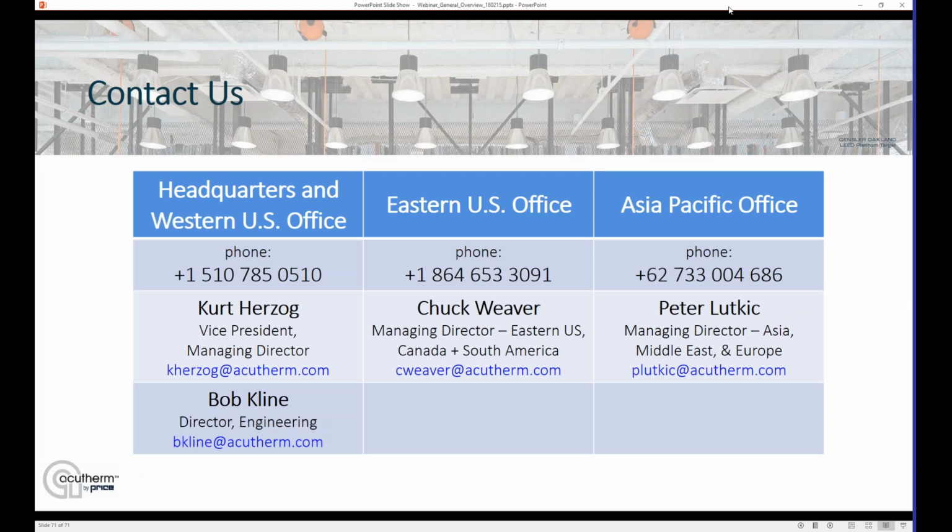Okay, let's see what we've got coming in. So where is the Therma-Fuser diffuser applicable and where is it not? Easiest answer there is if you're thinking a VAV system, you should really be thinking a Therma-Fuser diffuser system. If you've got, I don't know, something like a hospital, at least here in the US, hospitals require room pressurization and air changes per hour requirements, not a great application for VAV.